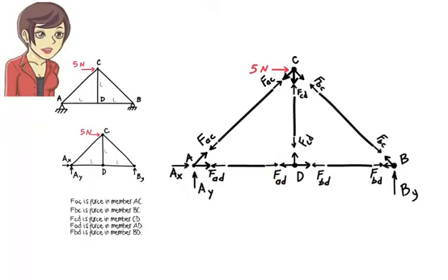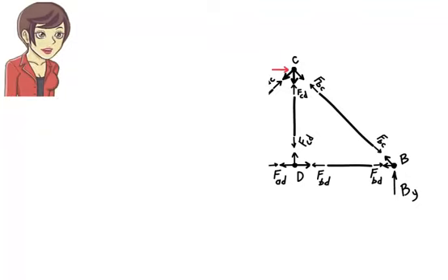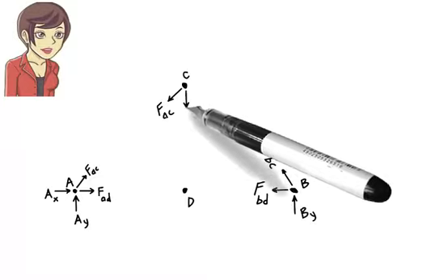As I mentioned before, for the entire truss to be in equilibrium, each segment must be in equilibrium. We can easily see that the equilibrium equations are satisfied for each member segment. The 2 force vectors shown in each segment cancel each other. That is, their sum equals 0. And since there is no bending moment or shear force acting on the free body diagram, the moment equilibrium equation is automatically satisfied. So now let's turn our attention to the joint segments.